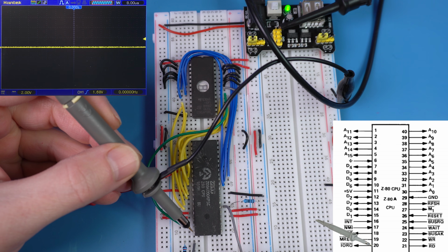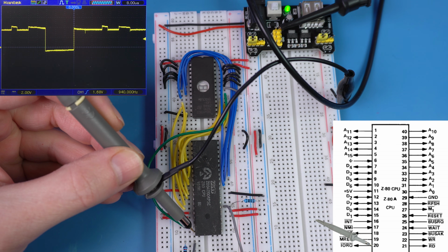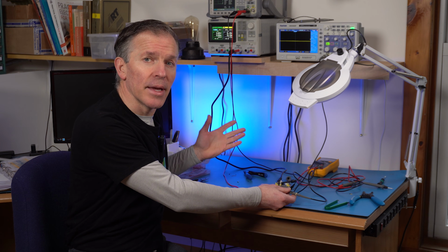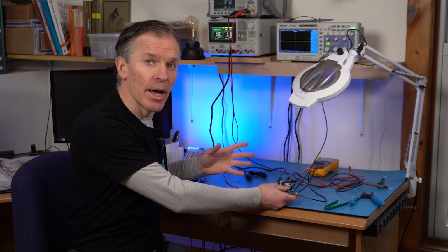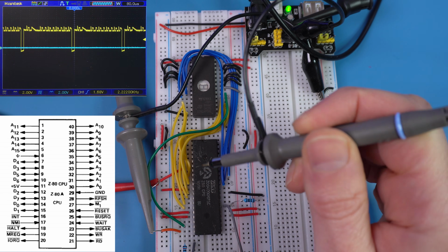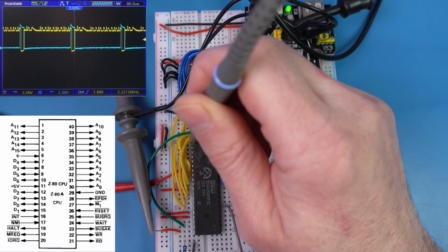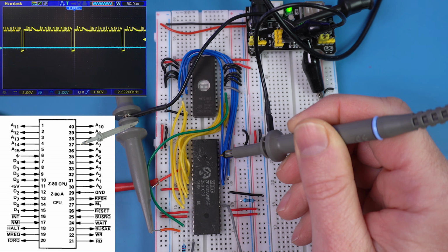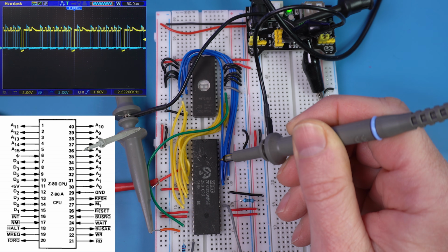And after I reset it, when we look at IORQ, there you go. You see that it periodically comes up like that. This is not ideal, but we can check out the address lines at the same time we're checking IORQ on the oscilloscope. And yeah, it looks like we're getting a 1 on every bit on the upper half of the address bus. And on the lower address bus, it looks like it's 0. So yeah, that seems to work.